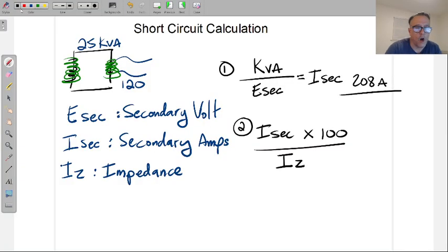So on average, you don't have to write any of this down, but little transformers, let's say, converting 120 to 12 volts, are going to have an impedance of about, an energy loss of about 0.5%, maybe 1.5%. It's very low. A really giant transformer for a big industrial place that's, say, converting 12,000 volts and stepping it down to like 480, this will have something about 8.5% energy loss. All right, you're working with big numbers now.